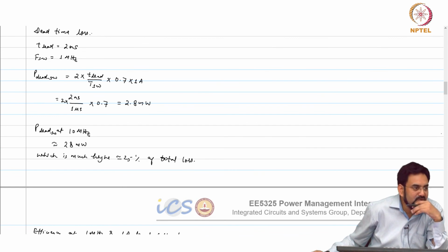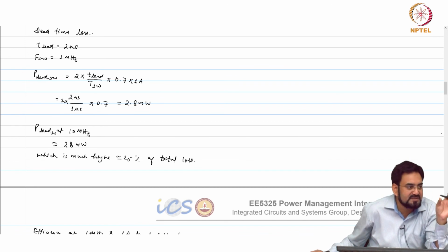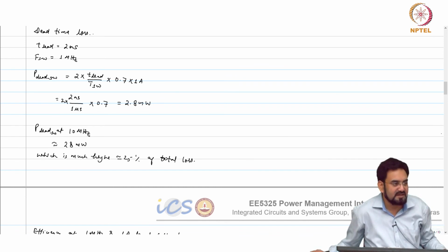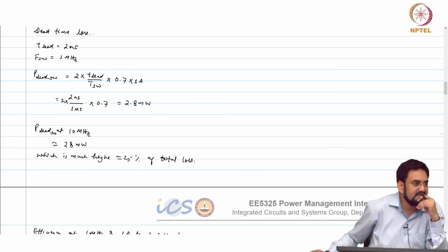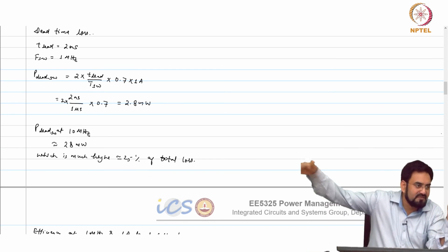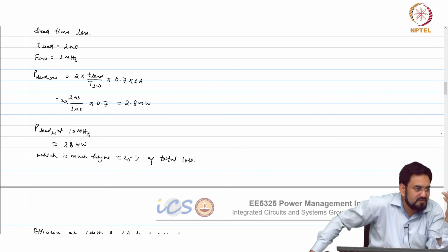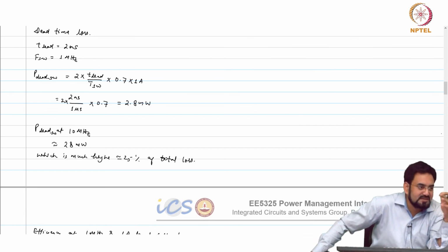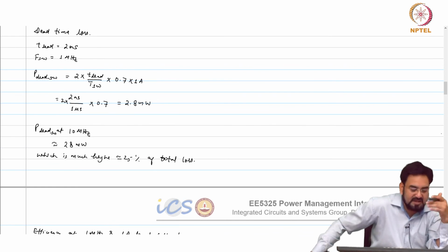So, that is why most DC-DC converters which are operated from a lithium ion battery, mostly used in cell phones, where the lithium ion voltage we know is like 2.5 to pretty close to 5 volt, 4.6 to 5 volt. So, this 1.8 volt or 0.18 micron does not work there. You need 5 volt devices, and operating at 10 megahertz there is not easy if you want to cater to 1 amp. 90% efficiency is very difficult. You may achieve maybe 85, 86%.